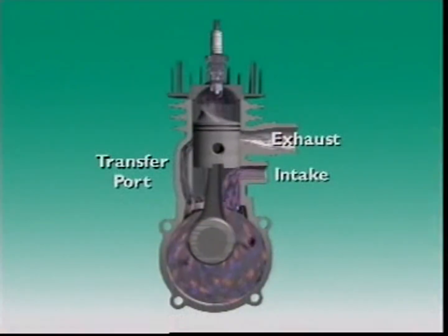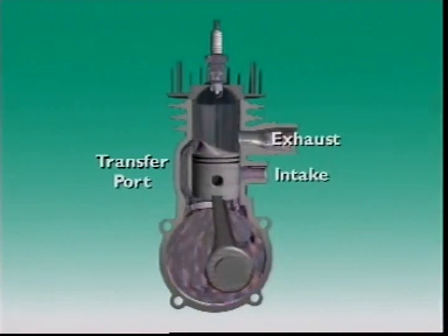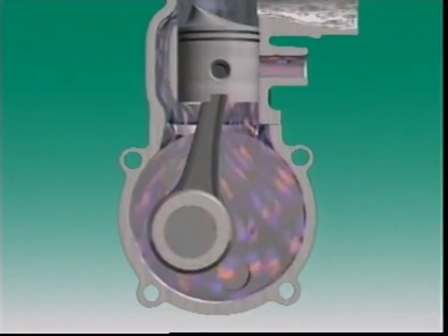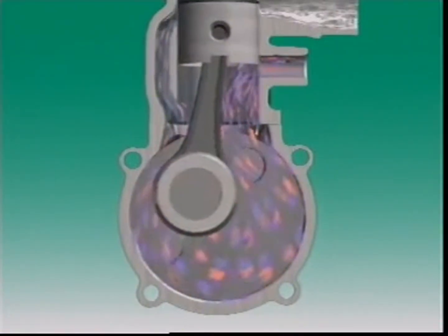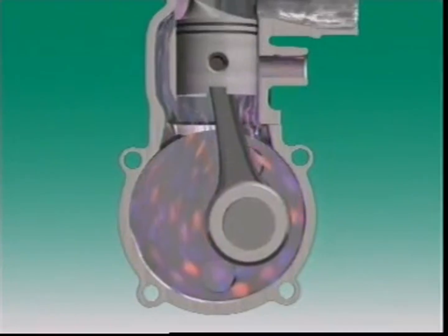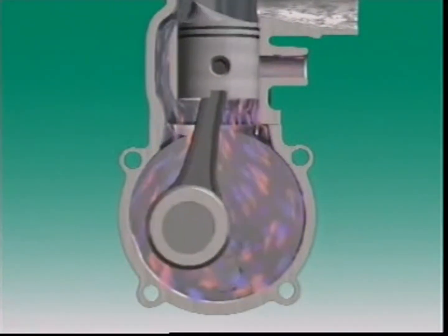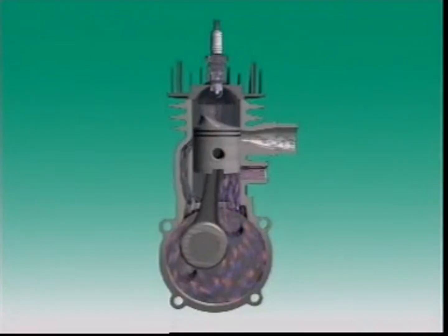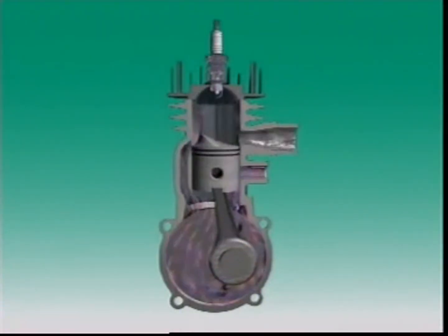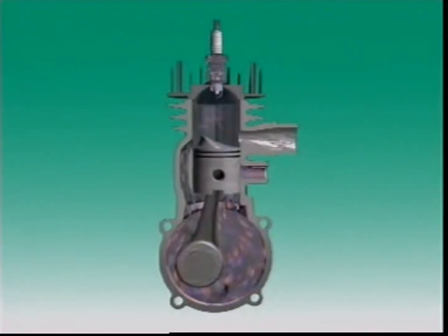For small two-stroke engines, the oil and fuel are pre-mixed. A mixture of air, oil and fuel passes through a sealed crankcase on its way to the combustion chamber. That makes the crankcase part of the fuel intake system, so it can't be used as a sump. As the air, fuel and oil enter the crankcase, the fuel evaporates, leaving behind enough oil to keep parts coated and lubricated.